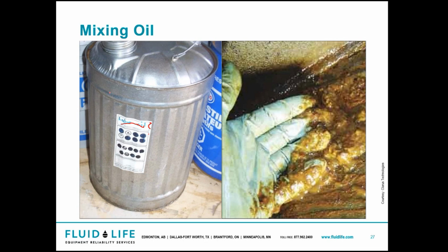It almost looks like a soupy mix you'd find on the bottom of a tank of oil or whatever. I don't really suggest mixing oils and greases for that reason, or two different oils, because it can be a real disaster.